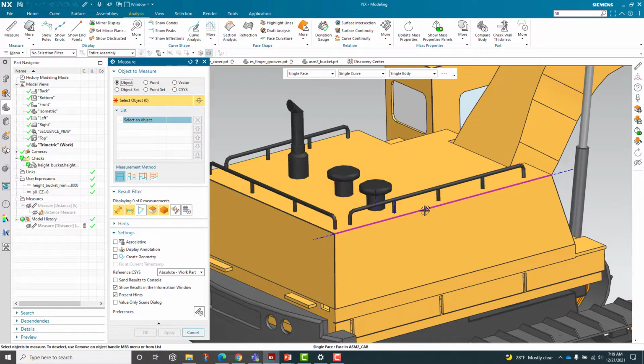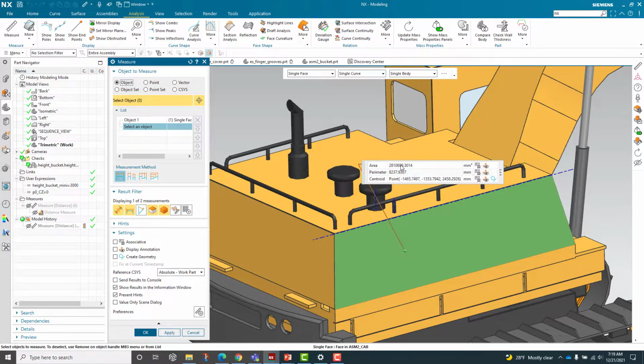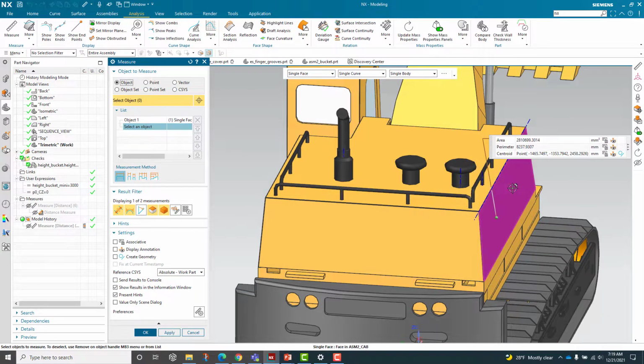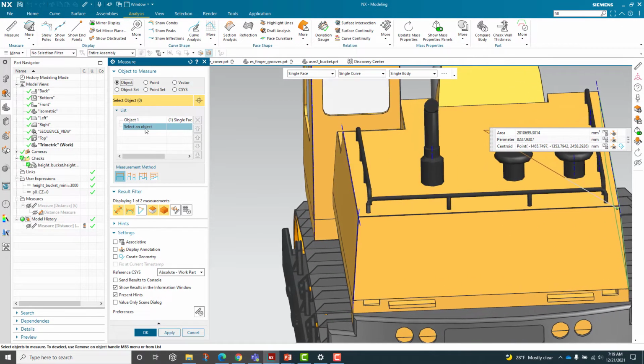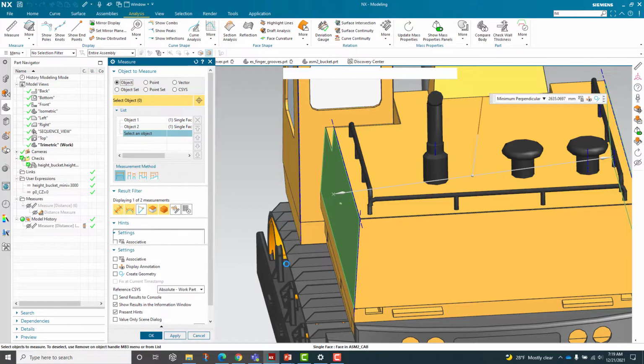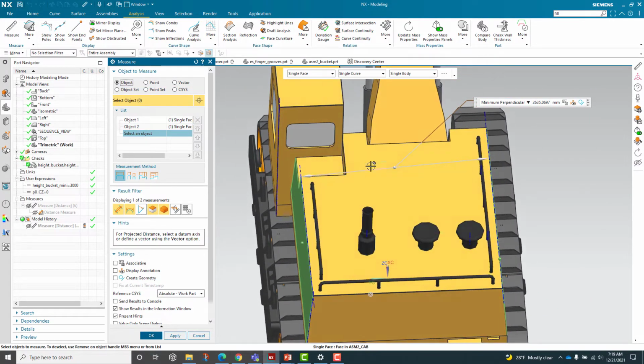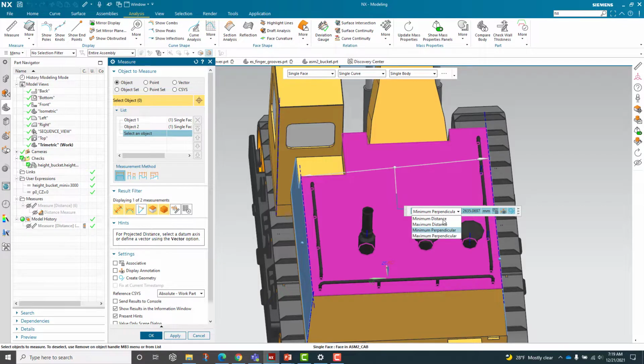So just holding our mouse over, it does give us some nice little options. Interestingly enough, you could simply click on it and it's going to give you those same options. It's just that now you could say I want them to be associative, or I want them to show up. Or for the center, I want to see what's the center point. For our purposes though, we're going to take a measurement from one side to the other. So we've got the first, and if you notice, I'm just adding, as I've said, to my palette. So I'll choose the second item, and it's given me a measurement.